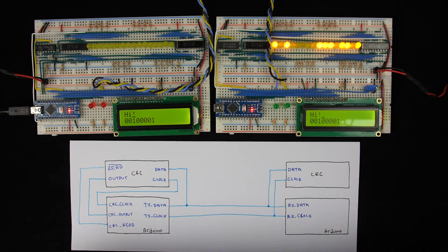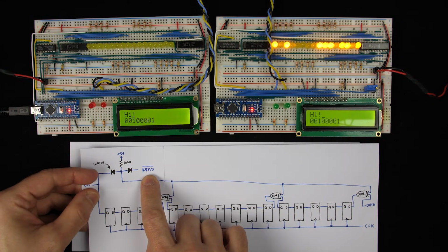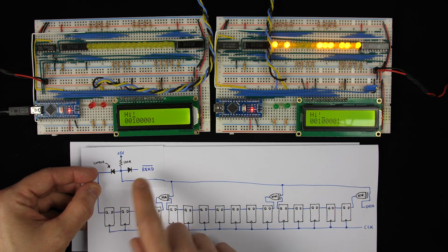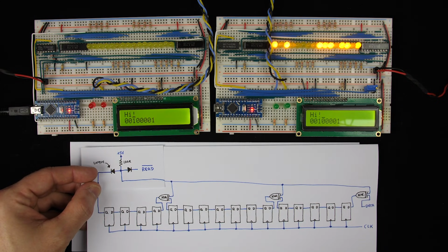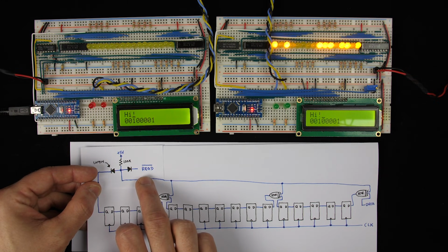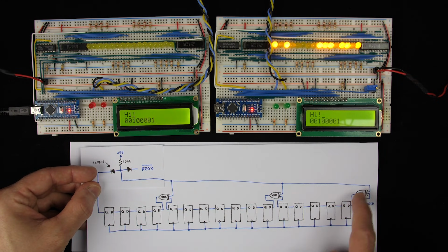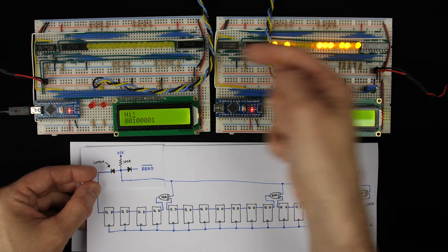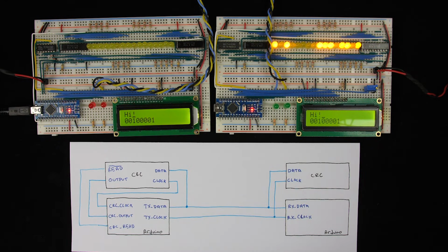And I believe that is probably because this read signal is probably telling it that we're in read mode, because I didn't actually do anything with that. And we probably need to set that high since it's active low. It's probably defaulting to low. And so everything we send in, it's not doing these XORs. And so it's just sending the data in and shifting it across. So let's look at the code and make sure we initialize that read signal high.